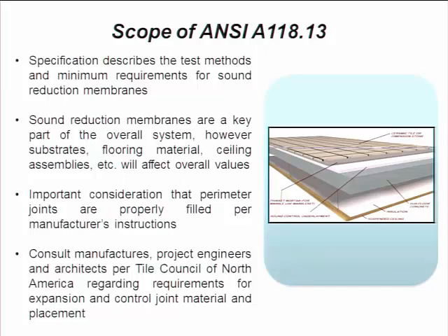Looking at the scope of the specification, it describes the test methods that are looked at in this specification, and are the minimum requirements. Sound reduction membranes are a key part of the overall system, and this is important to remember. The membrane isn't the only thing that's giving you the result. It's your entire system that has an impact upon your sound performance.